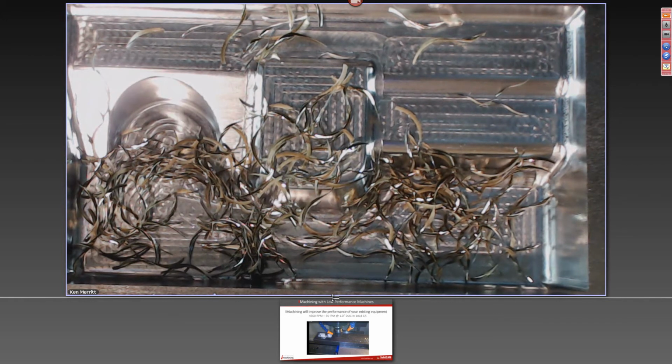What's the worst thing we can do to carbide? Is shock it, okay? Whether that's a thermal shock from hitting it in and out of coolant, whether it's a vibration shock from creating harmonic vibrations, or whether it's an impact shock by not bringing it into the cut smoothly, the worst thing we can do to carbide is shock it. It'll fracture the substrate, okay? So everything we're doing in iMachining is designed around keeping the load on that tool extremely consistent so your tool life goes up even though you're getting increased performance and productivity out of the cut.